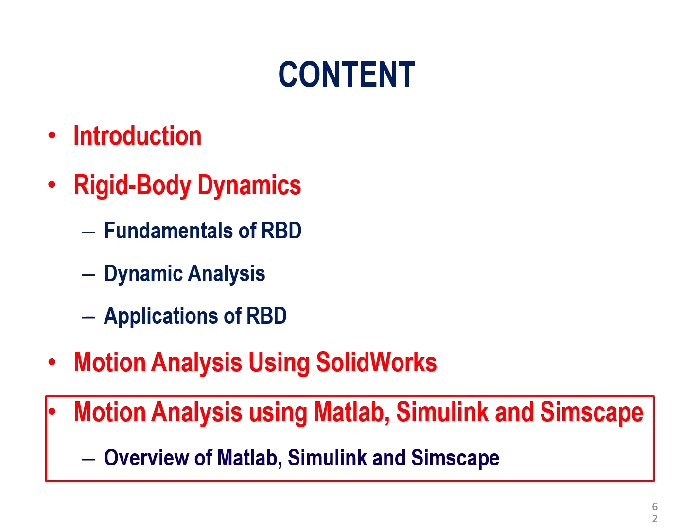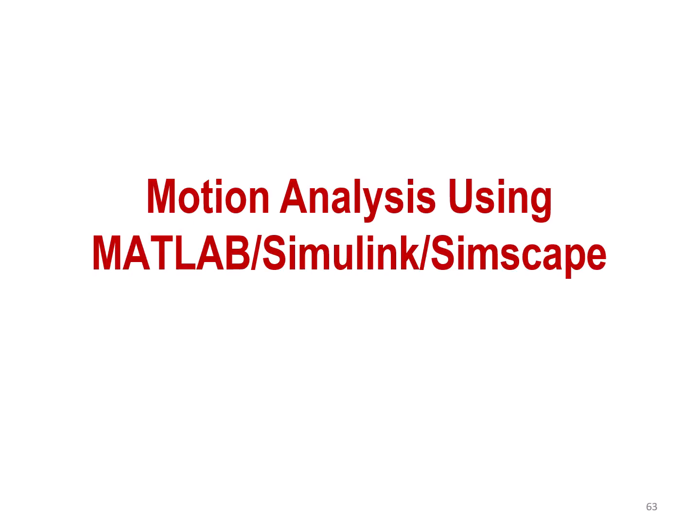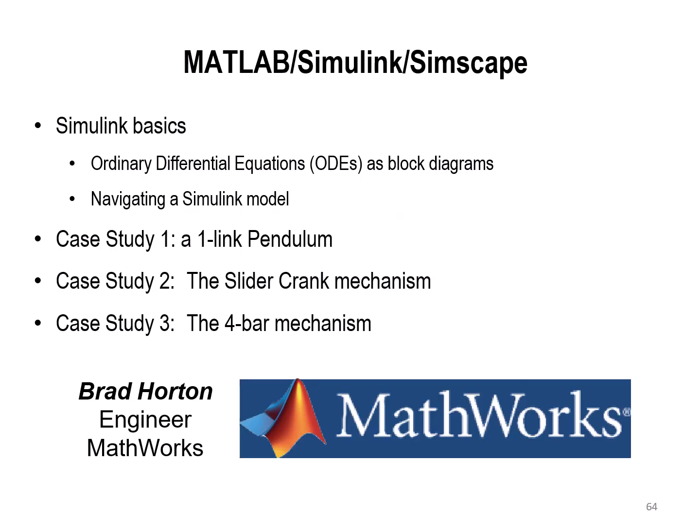Now, the last part of the session today is about the motion analysis using MATLAB Simulink and Simscape. This is actually what we're going to do in the lab over the next 2 to 3 weeks. The Simulink basics will be covered, the ordinary differential equations as block diagrams, and navigating the Simulink models. Case study 1 is going to be a one-link pendulum, case study 2 is the slider-crank mechanism, and case study 3 is the 4-bar mechanism.